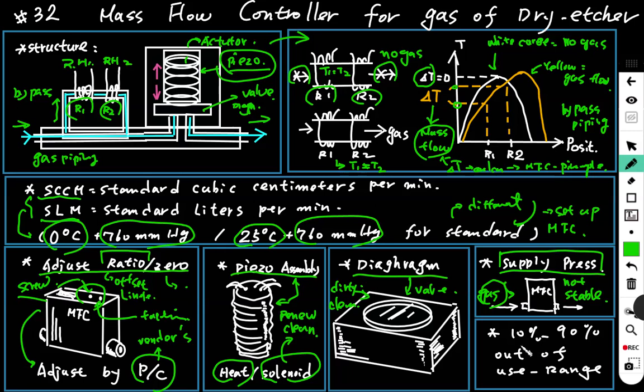And then maybe you use the wrong range. Often the MFC is designed for 10% to 90% accuracy.